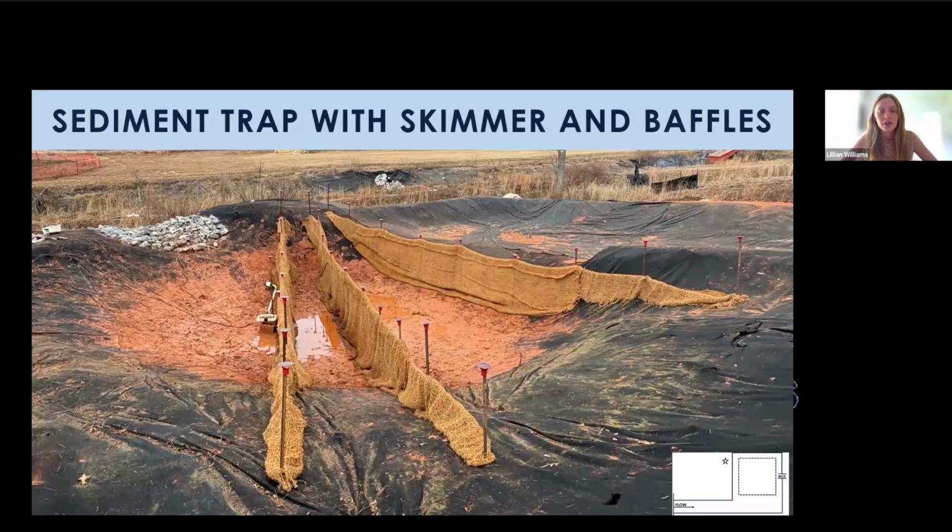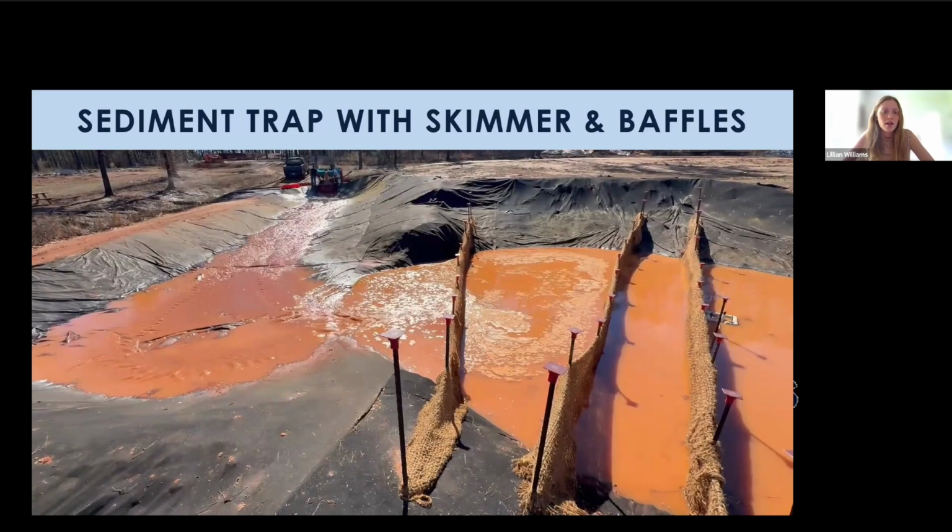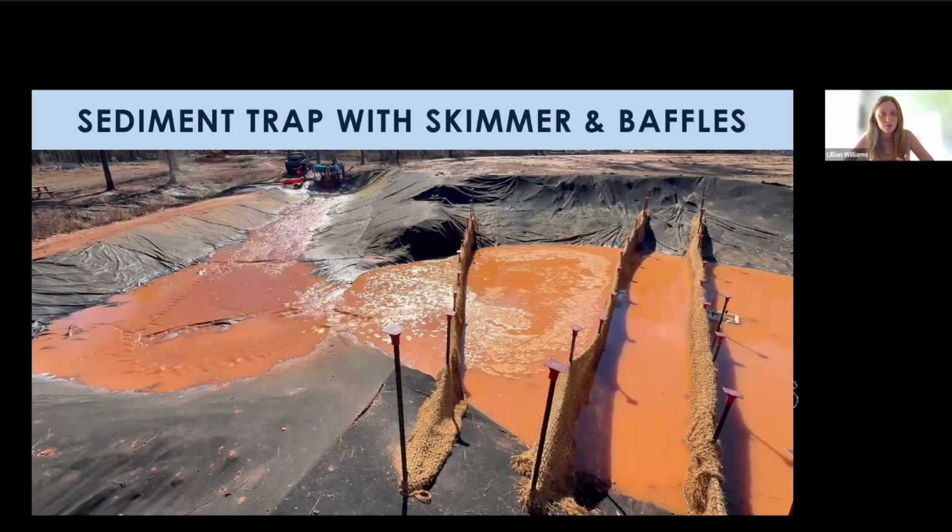And then our MFEI we determined was going to be the baffles because of that slowing down feature that we had noticed in the video, and then the skimmer because it would restore volume. The spacing's a little bit funky because I was following where the other baffles were. However, because I added a skimmer, I had to scrunch that last one because the skimmer needed to be in the deepest part. But you can see that our baffles were not overtopped or bypassed, and the skimmer's hiding, but it's going to start restoring that storage volume. And this was the same kind of slowing down effect that we saw.